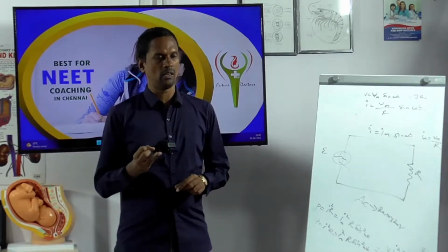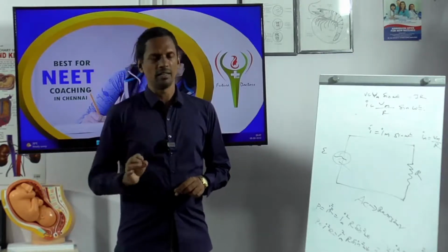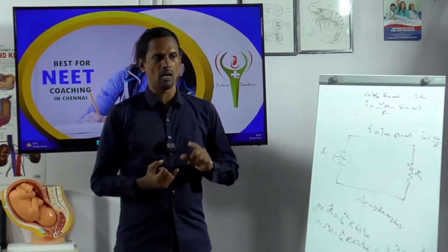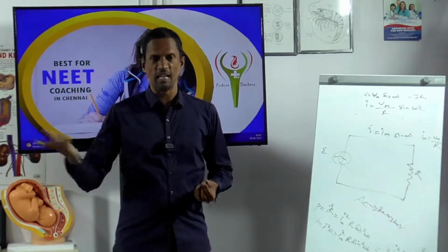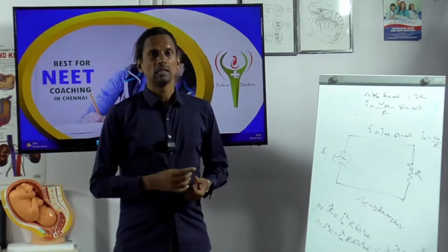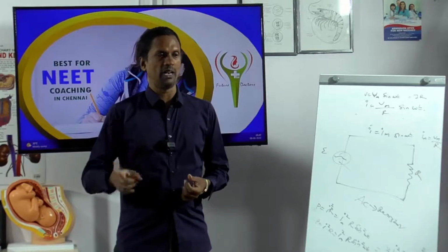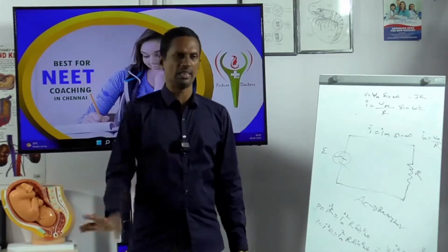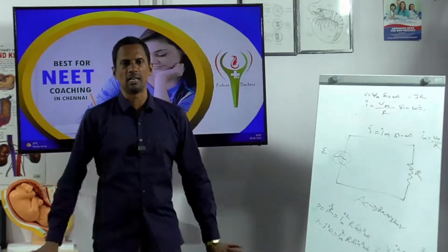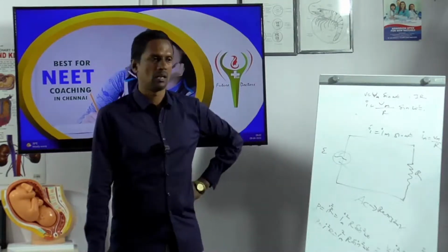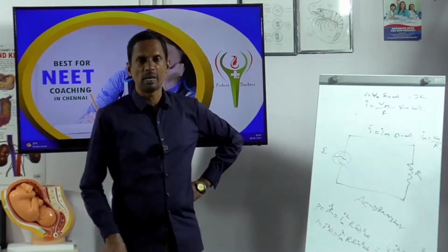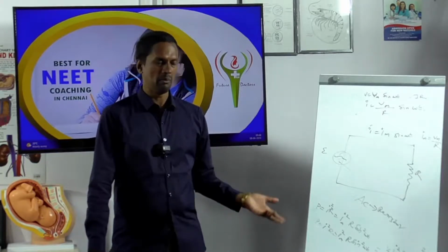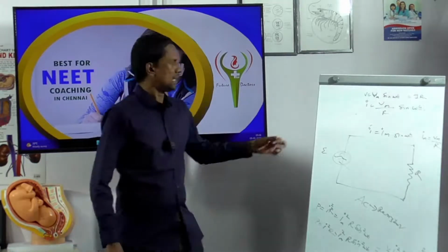The AC and the water heater or geyser in the bathroom will be 15 amps. So these two are 15 amps, and all other things can run on 5 amps. Which is maximum here? 15 amps is the maximum. Minimum is 5 amps. So that is the difference.